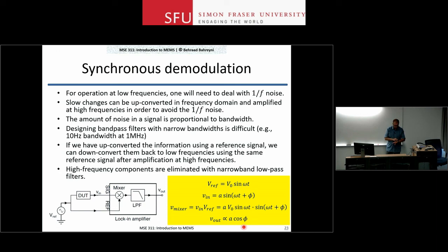This is your only technique to measure low noise measurements with very small bandwidth, and it's used extensively in a lot of test instruments, and if you want, you can actually implement it using relatively simple digital and analog electronics as well on board. Some of these functions, like the mixing, like the filtering at the end, can actually be done digitally. So that's that for the noise and interfacing section of the course, and I'm going to post an assignment soon so that you have some, let's say, warm-up questions.